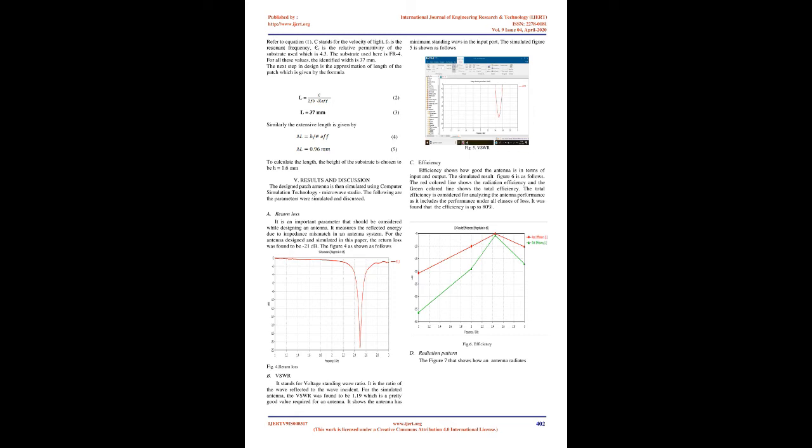B. Coaxial feed. A common technique to feed a patch antenna is the coaxial feed. This type of feed consists of two coaxial connectors, namely the inner connector and the outer connector. The inner connector is connected to and soldered to the patch.